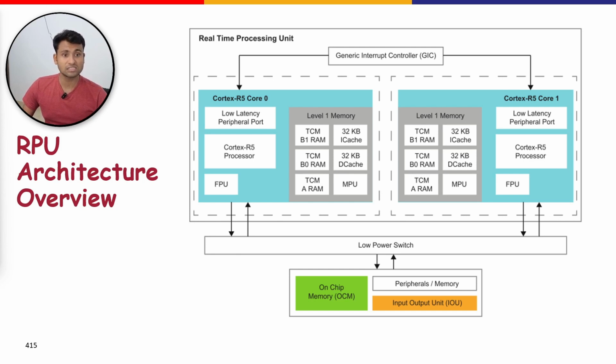Carrying out instructions in this manner provides redundancy, as if there is a mismatch between the output of the two cores, then an error has occurred. So this lockstep mode method of processing allows more safety based processing, and is also known as safety mode because it allows the system to determine errors effectively if the two outputs are not matching. There are also ECC schemes. ECC stands for Error Checking and Correction scheme, which also provides further error detection and correction support.